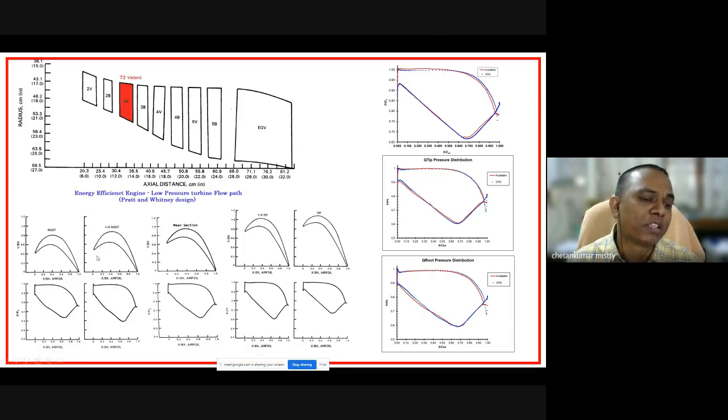Now, the shape of my leading edge and the shape of my trailing edge is of a proprietary nature, and that's the reason why those data are not available openly. Based on our number of iterations, we are able to achieve the flow acceleration and deceleration on the leading edge and on the trailing edge. So you will have some discrepancy here, but that is within the range, maybe plus or minus 2%. So that's accepted.